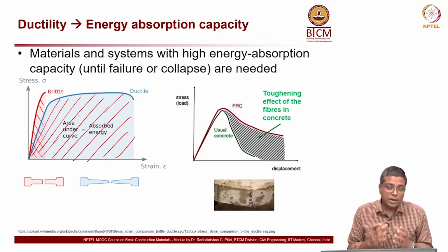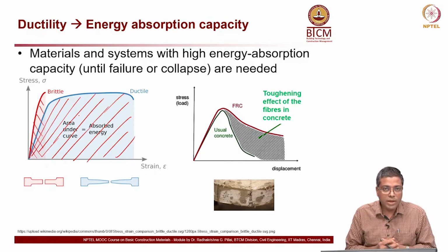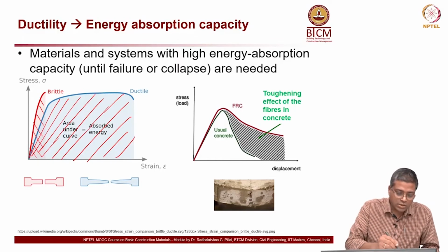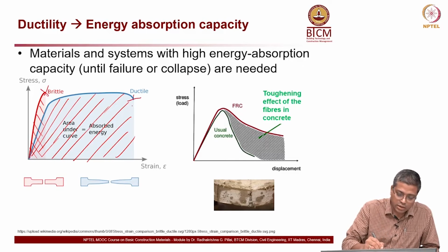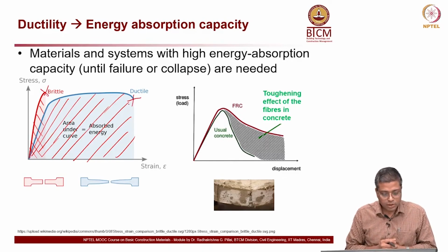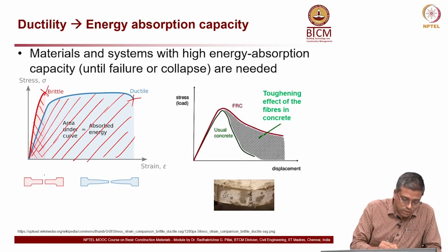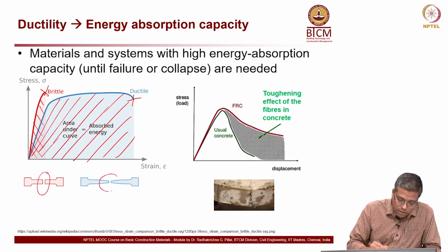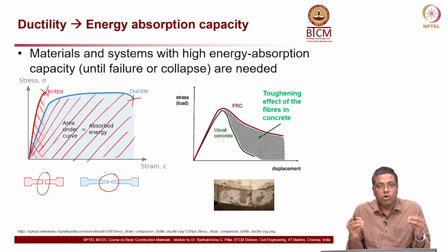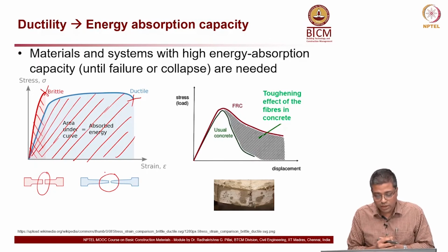So, that means that the ductile material is able to absorb more energy before it fails or fractures. Fracture happens here and here in these two cases. Okay. So, here also you can see brittle material, no deformation, ductile material very clearly gets elongated and necking is happening and then eventually it fails.